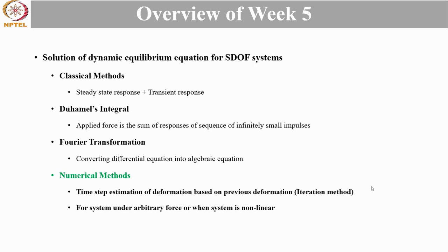Then we saw Fourier transformation, in which we convert an ordinary differential equation into an algebraic equation and see the response in the frequency domain. And finally, we have the numerical method, in which time step estimation of deformation based on previous deformation is done, and it is a kind of iteration method. These methods prevail for systems under arbitrary forces or when the system is non-linear.